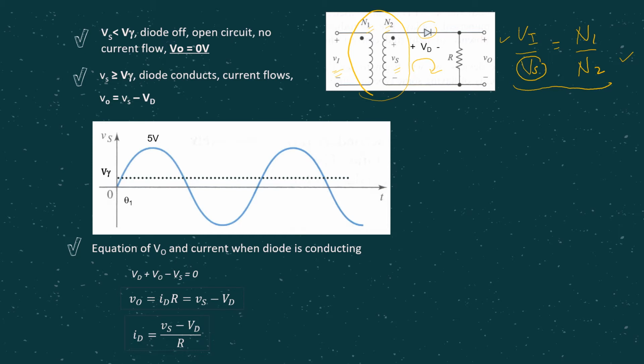Okay, then coming to the diode analysis. As I mentioned to you before, normally for the rectifier case, we consider cycle by cycle. So let's have a look at the first half cycle, where we have the positive voltage here, right? So in this case, Vs can be represented with positive and negative like this, meaning to say the positive is connected to the positive terminal, the negative is connected to the negative terminal. So in this case, the diode is forward bias.